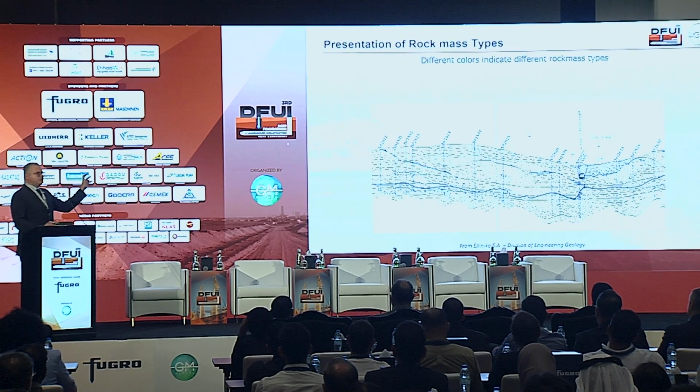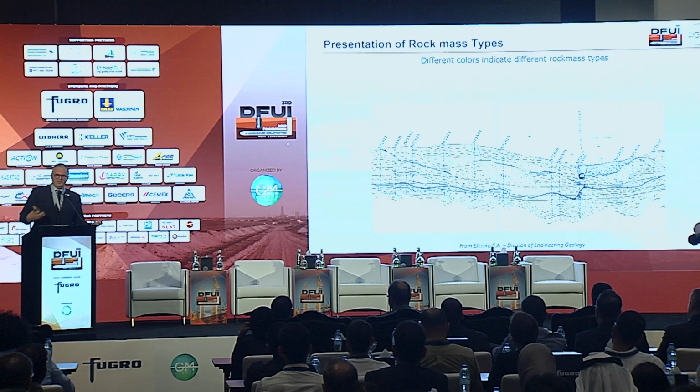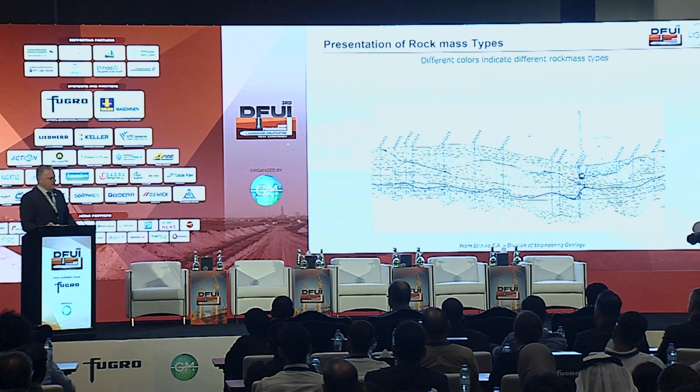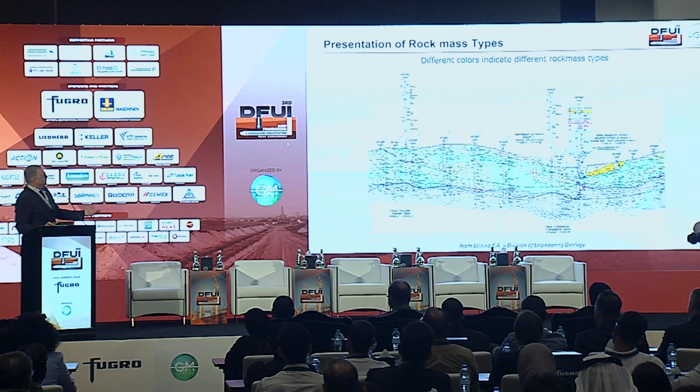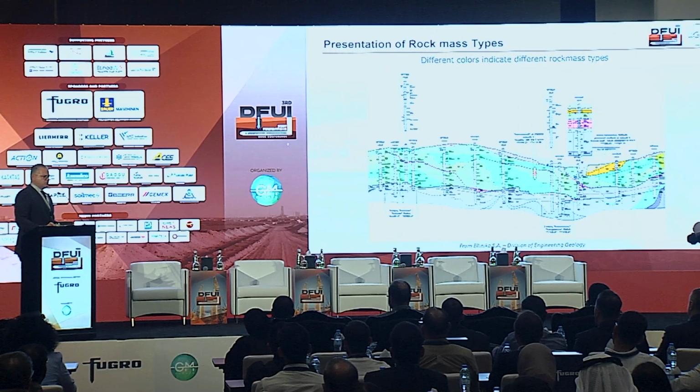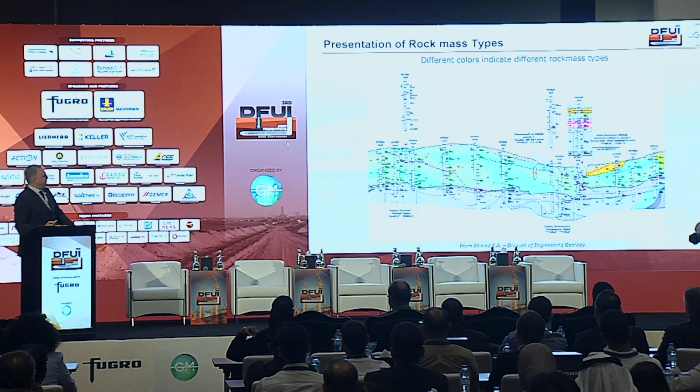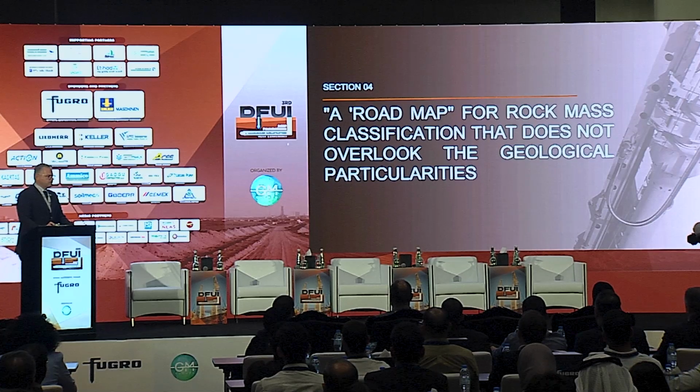So this initial geological model that the engineers don't feel very comfortable proceeding with into geotechnical engineering can be transmitted to the geotechnical section by putting in a set of GSI, sigma CI, and MI, so intact rock with the GSI, and then we know what to encounter and how we can proceed with our analysis. So we need a real roadmap.